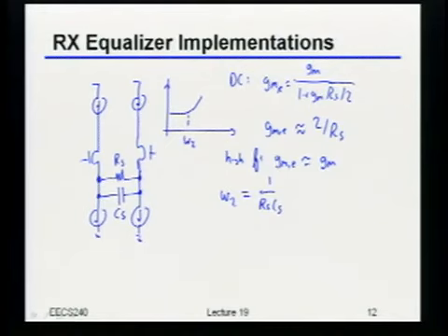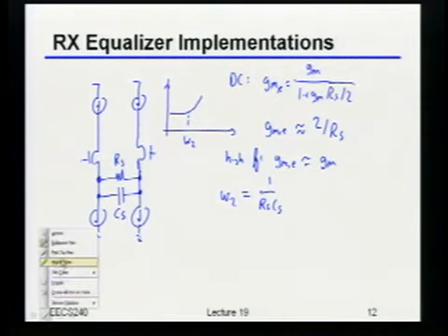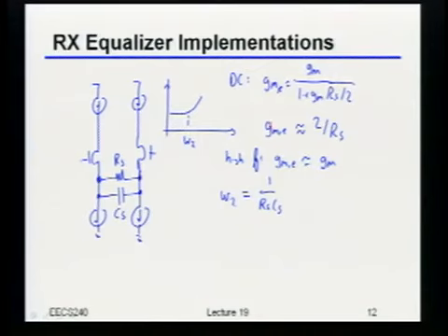Okay, so now remember, as I just explained a second ago, I can't get infinite gain at high frequency. Or to say it another way, if at DC this was my effective GM, at high frequency this is the maximum GM I get, right? So just based on that, what's going to be the pole introduced by that degeneration network? What's that going to be set by? GM over CS? Okay, you actually got the right answer.